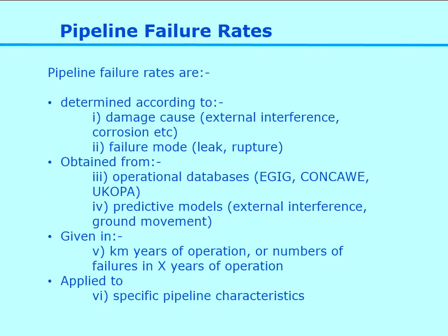Right, so failure rates. Failure rates are basically reported according to the damage cause, which is the cause that has resulted in either a leak or a rupture, and they're obtained from operational databases. If you're going to do risk assessment, you must have a good reference source for your failure rate, and therefore you've got to use a recognized database.